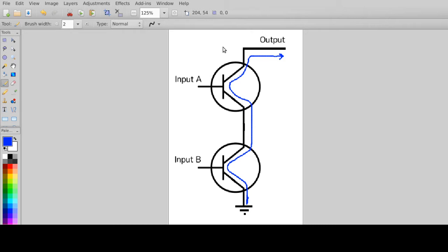All right, now it will do that provided that you don't apply any electricity at either input A or input B. Only if both inputs A and B are zeros will you get electricity coming out here like that. And so maybe I can summarize it down here. Let me see if I can build a little table down here. If both A and B are 0, like that, then you get a 1 coming out. So this is input A, there's input B, and there's your output. Okay, I think you can see that. It's a little small, but it's good enough.